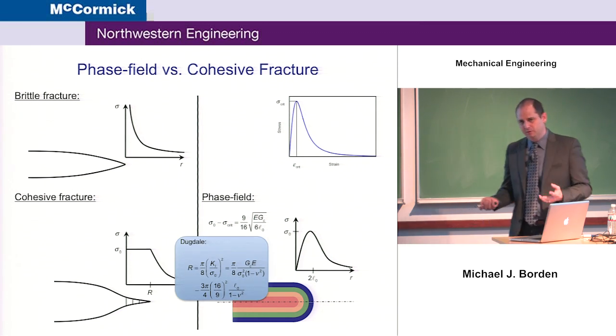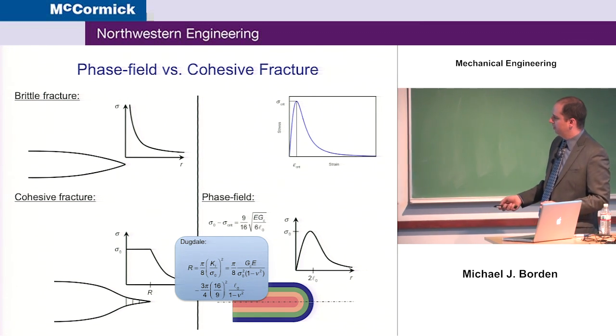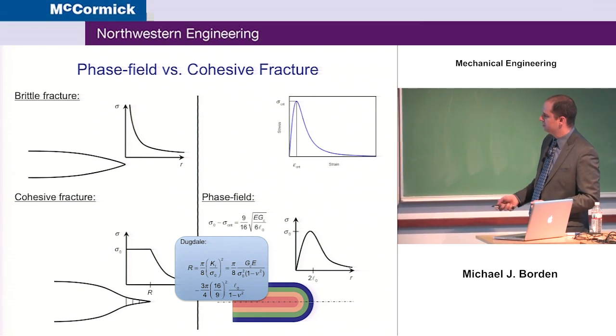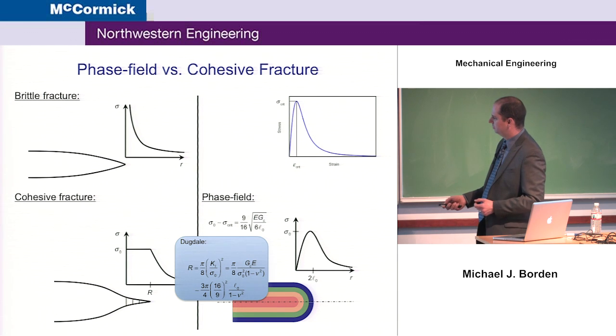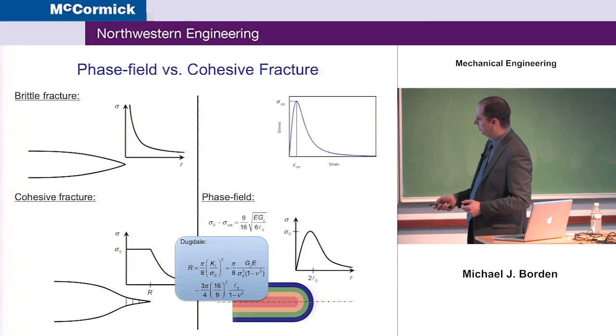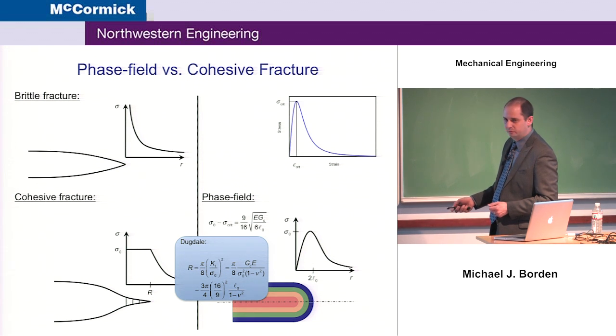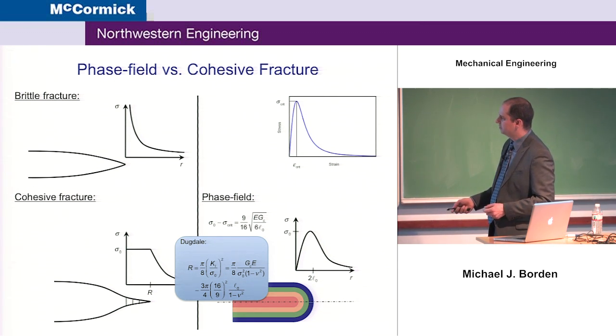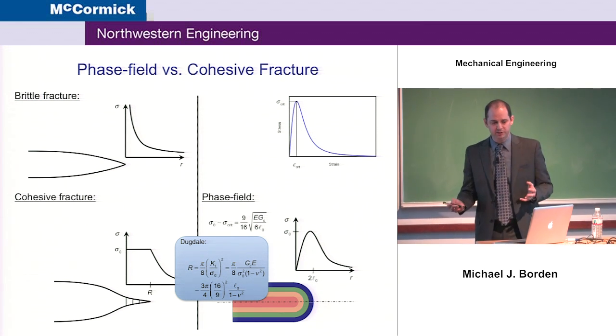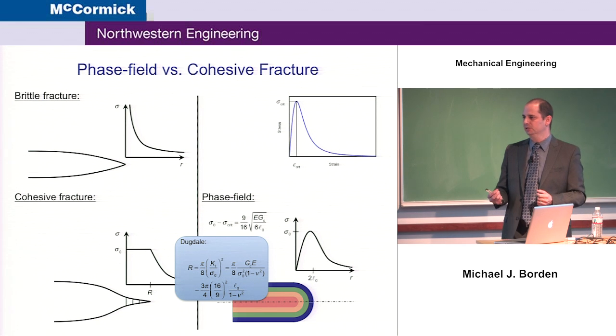And if you look at a model, say for instance a simple Dugdale model, where you have this process zone as a function of our stress intensity factor, we can rewrite that in terms of our other material parameters, this crack energy density function, our Young's modulus, and also this peak stress. If we approximate this peak stress with this critical stress, we get a relationship between the process zone for this cohesive model and also the process zone, L naught, for our fracture model. So there's some relationship there. We haven't really figured out all the details of it.